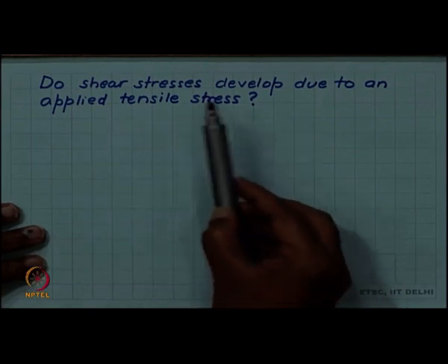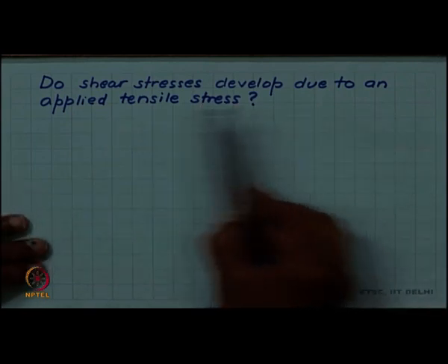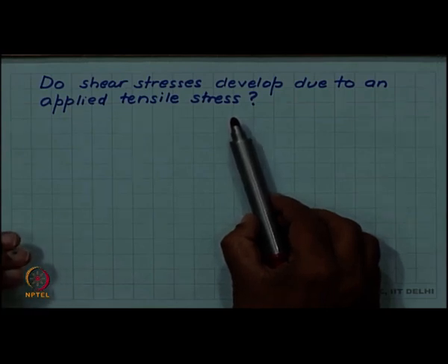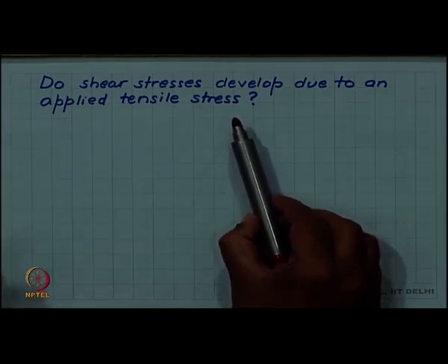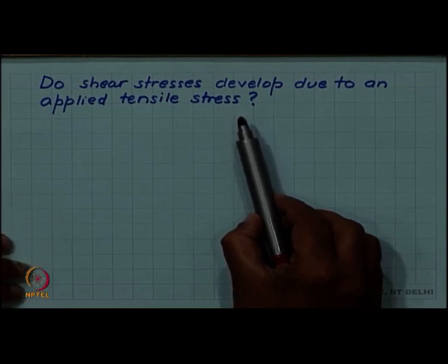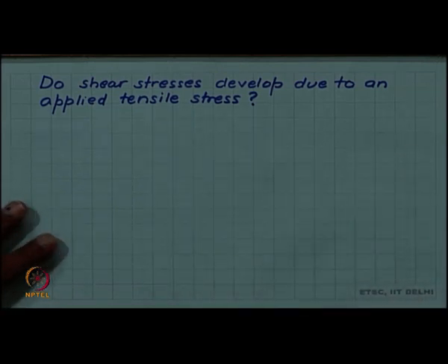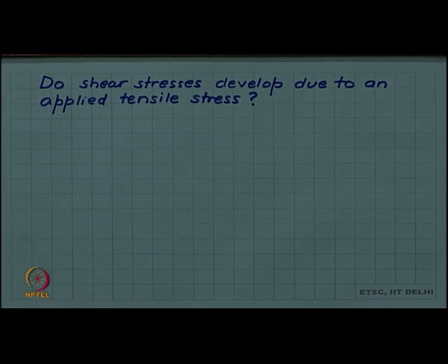We have a question: do shear stresses develop due to an applied tensile stress? Because if slip is the mechanism of plastic deformation and tensile stress is causing the plastic deformation, then that tensile stress should be capable of generating shear stress on the slip plane in the slip direction.